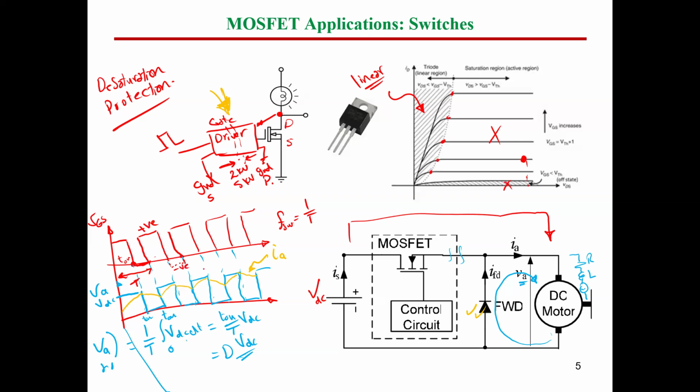Why do we prefer to do that in industry? Because of a lot of aspects. One of them is that when you make a PCB, your ground may not be exactly 0 volt, and this may not turn off the MOSFET completely. In order to be sure that the MOSFET is completely turned off, we can apply a negative volt.